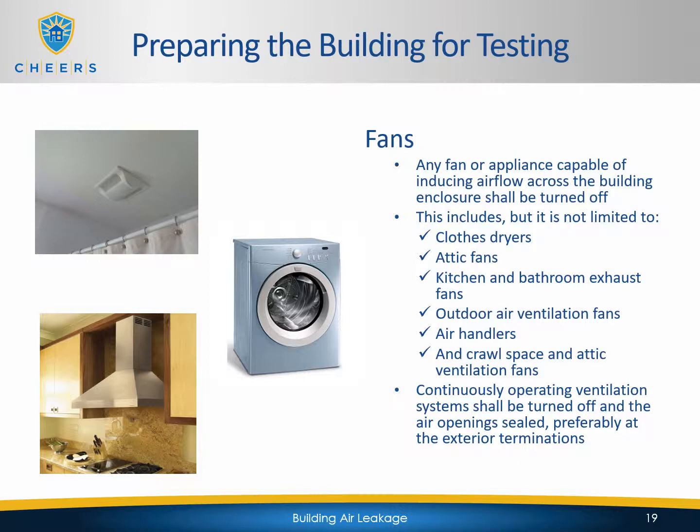So keep in mind that's continuously operating ventilation systems, so not the intermittent fans that you see in a bathroom or in a laundry room necessarily. That exception to be turned off and sealed, keep in mind that's only for continuously operating ventilation systems. It's very specific.